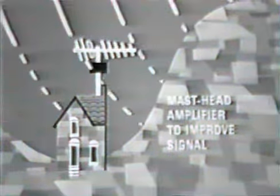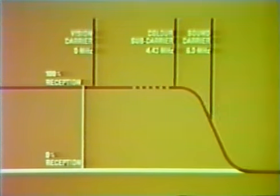From insufficient signal, we move to incorrect bandwidth. It is important that the response at the color subcarrier frequency is similar to that at the vision carrier frequency. If the aerial bandwidth is incorrect, one or other of these will probably be low. An aerial chosen for the correct group of channels in your area should be used.